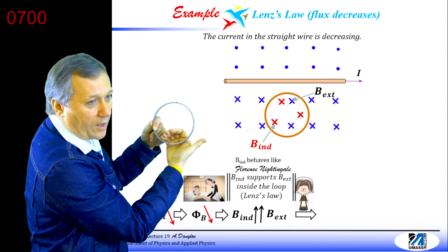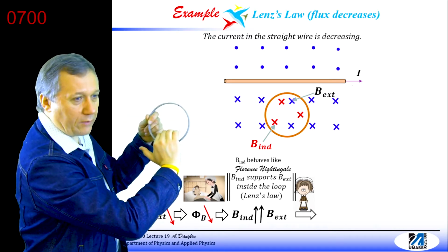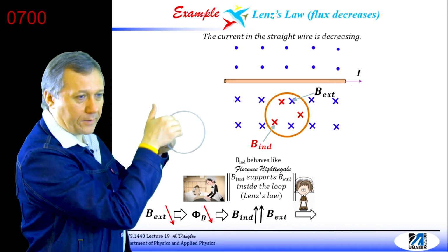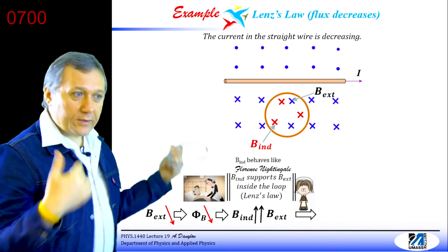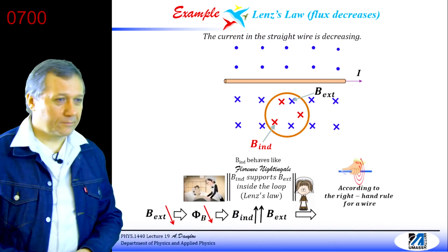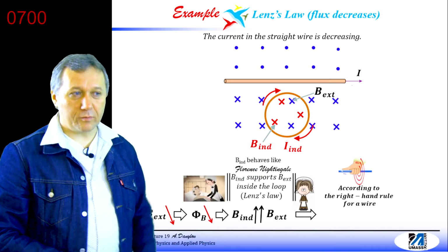You see my fingers are out of the screen, although our induced magnetic field is into the screen. So I have to position like this, sort of wrapping the wire. Right. Okay, so this direction, clockwise direction, right? So as a result, I induced in the clockwise direction.